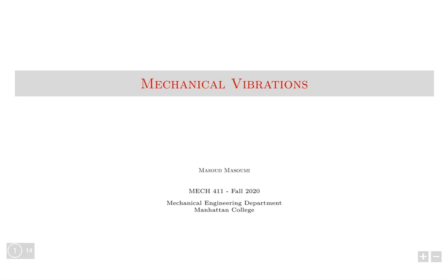Now, the Lagrange method, I wouldn't say as opposed to Newton's method, but different from Newton's method. You don't really need to draw free body diagrams, or worry about whether you're taking the direction of the motion correctly, or whether you're putting the forces applied from the springs to your mass correctly. You don't need to worry about that part. It's more math. You are taking advantage of math and the fact that the energy of the system is changing during oscillation. Knowing kinetic and potential energy, you can actually derive the equation of motion. How does that work?